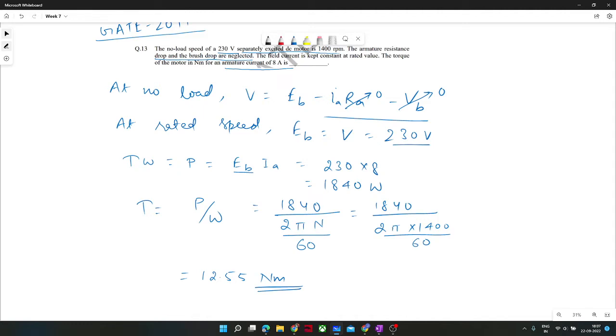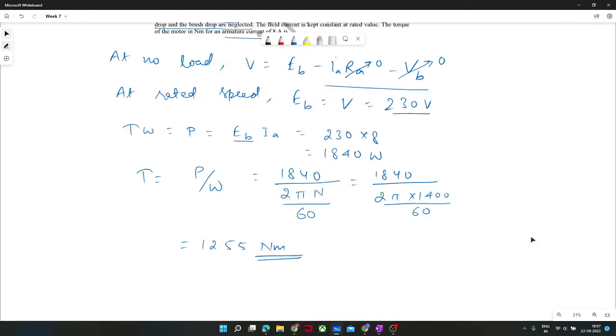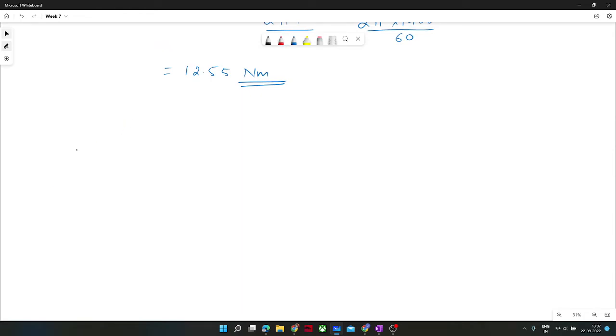Not quite, because the drop will also be in between. If the current is there, then input power minus copper loss will be the developed power corresponding to that speed. I have shown that power flow diagram in, I think, the synchronous motor. Electrical power goes in to develop some mechanical or developed power, which is electromagnetic. There will be some copper loss due to current, whatever the load or fraction of current at which it is operating.